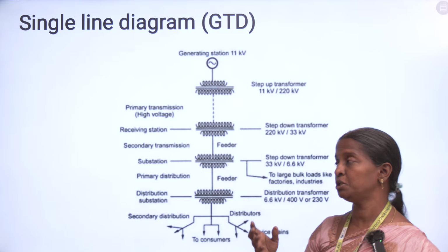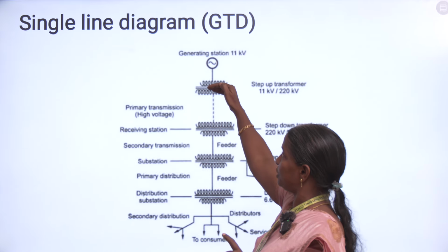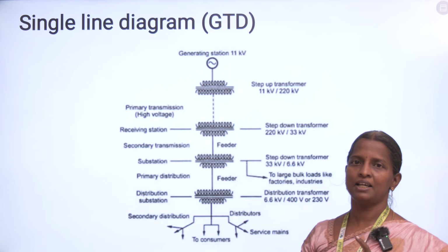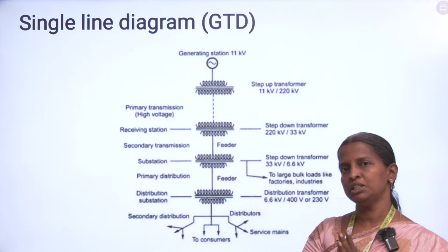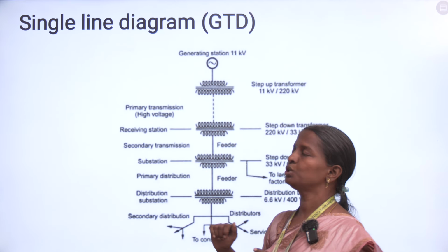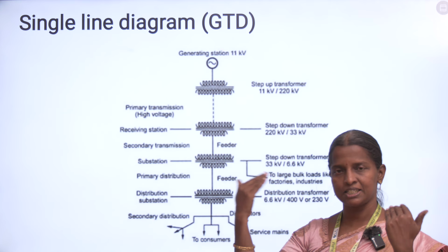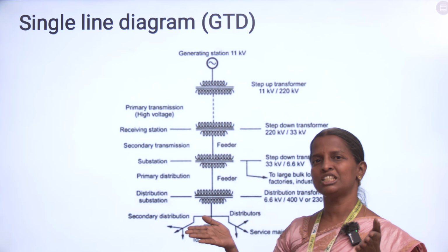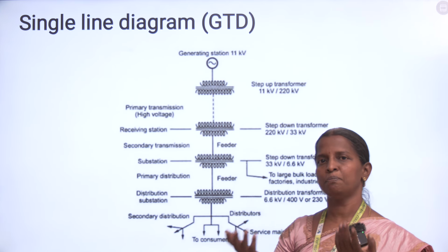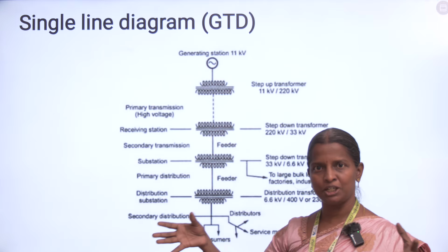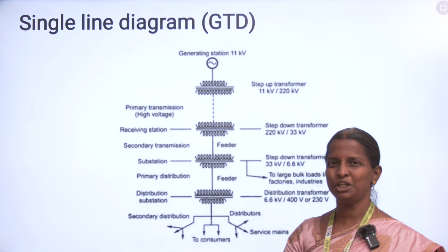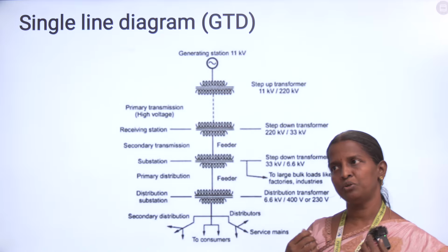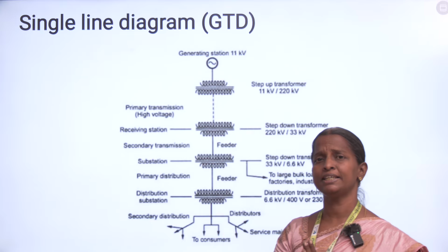So where is it produced? If you give 11 kV to the primary coil of the transformer, it will produce the magnetic flux. Okay. Next, we have the iron core. So what is the use of the iron core? If there is a path for the flux, the intensity will be maximum. If you do not provide a path, the flux will be spread out. So the density will be reduced, the intensity will be reduced. In order to avoid that, we use the iron core.